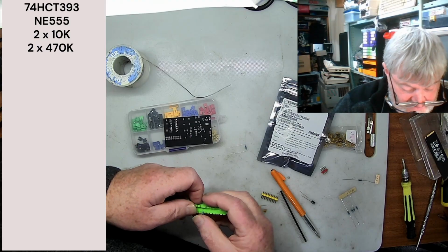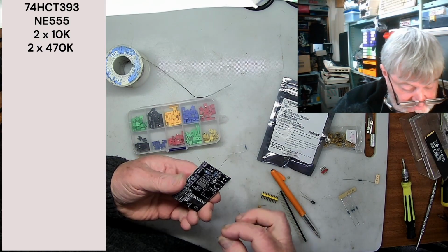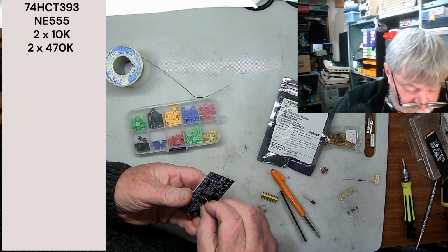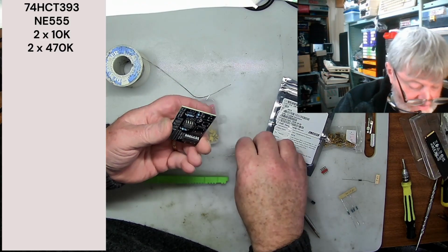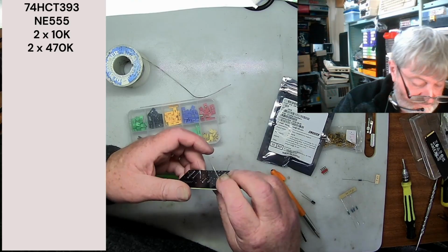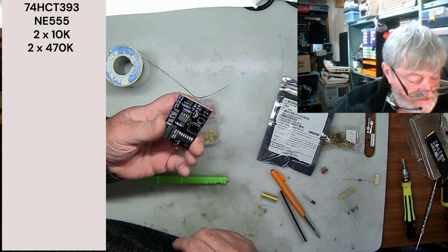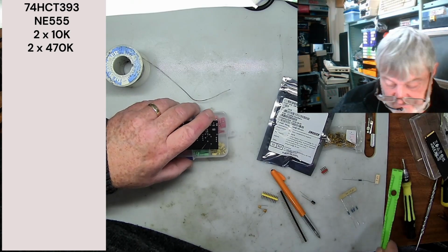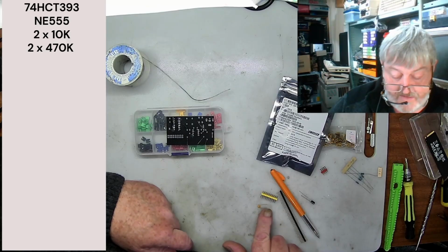And that one and that one, and we'll just pop those back out, and we'll put those ones in. So we've got a 470 over here, blow those out, and a 470 over here, and blow those out, and there we go, guys. So we got our resistors in there now, so we will go through and solder those up, and then I'll come back and we'll put the caps in,